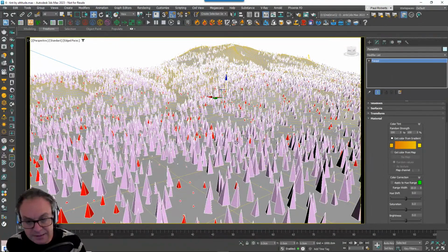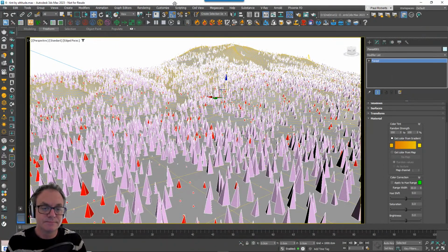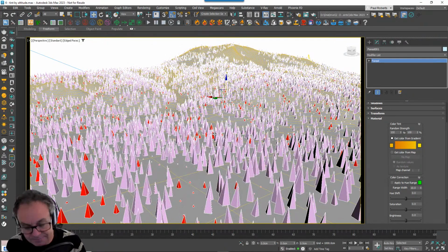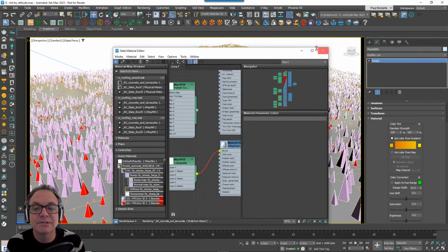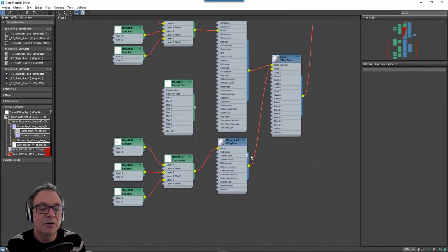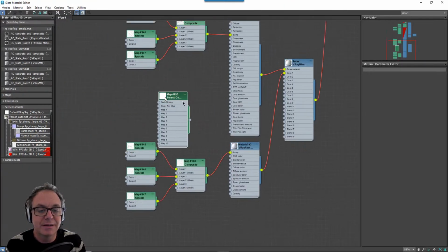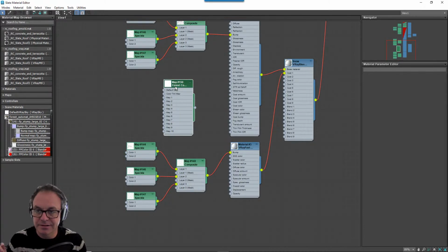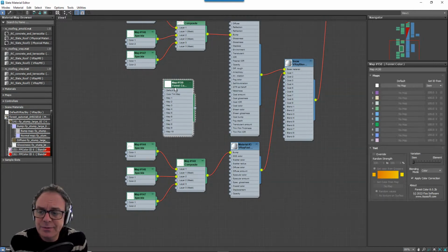And then in the materials itself, just open the material editor. Here it comes. And in the material itself, you just use your forest color map here as a mask. Okay, so you can use this for anything, anywhere where you want to mask between two materials. I'm just happening to turn off the snow on these trees, but you could use it for anything between two values. So it's going to output black and white, but that's what we want for a mask.